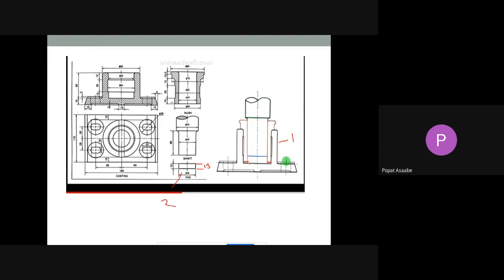45. Okay, so how much can we take from here? From the vertical line, yes, 22.5 in this direction, 22.5 in this direction. Okay, fine. We drew this, and what height did they give? They gave 13. I take the 13 mm from this 3 mm gap point. Okay, I took this and joined it. Okay, this will be the gap and this will be your pad here. This is part number 2.